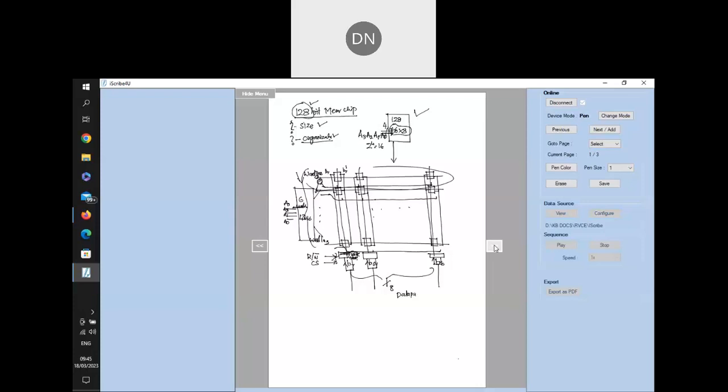Now if somebody asks how many pins are there in this particular chip, we can immediately say 4 address lines are there, plus 8 data lines. Similarly, we have 2 lines, one for the read/write bar and the other for the chip select, and 2 for the power supply, one for VCC and the other for ground. So totally 4, 12, 14 and 16. So I can just say 16 pins.